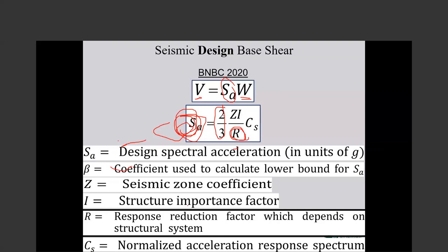So what can we do? Do we expect every engineer that wants to model a building for earthquake to do such sophisticated modeling? No. We say do simple modeling, but we put some design requirements so that this element never gets damaged in that mode.